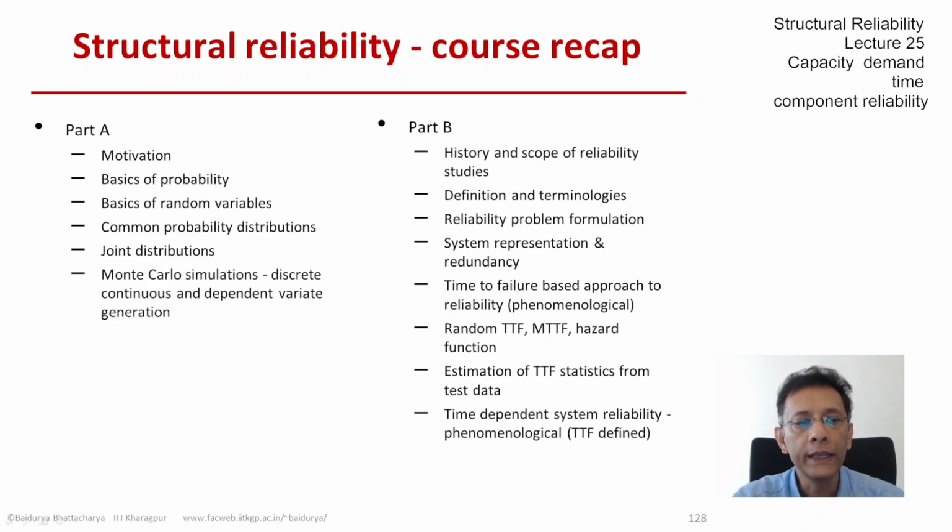Then we spent the rest of part B taking the time to failure based approach to reliability, and we called it phenomenological, meaning that the TTF is the only random variable that we have in describing the reliability or the uncertainties in the aspects of the problem. So we looked at components and we looked at systems. The system time to failure was defined in terms of the element times to failure, and we discussed reliability functions, hazard functions, mean time to failure, and so on.